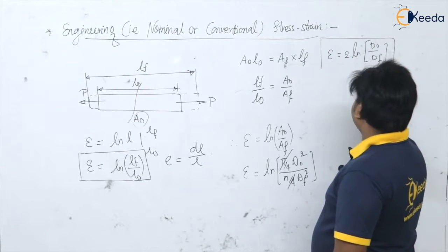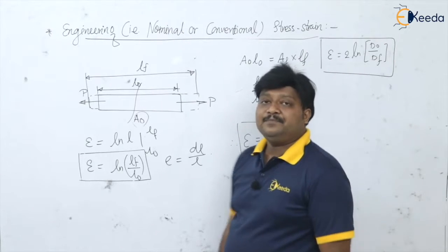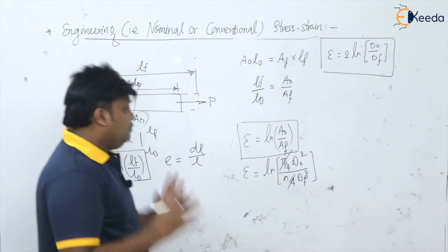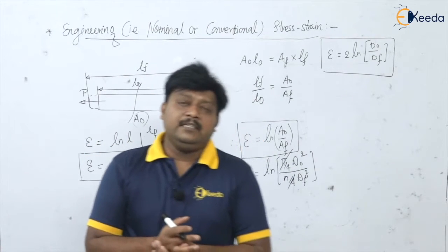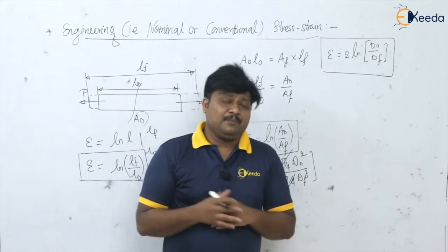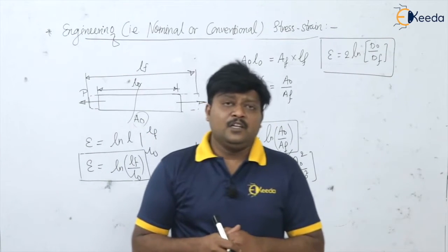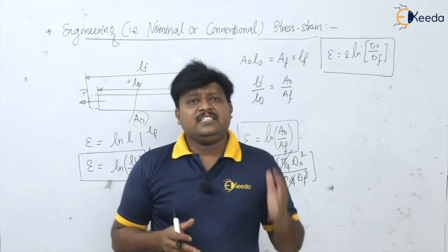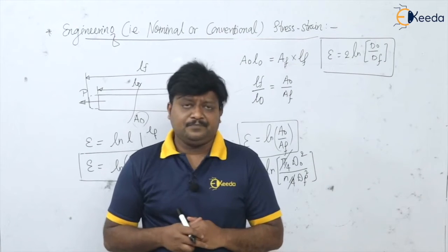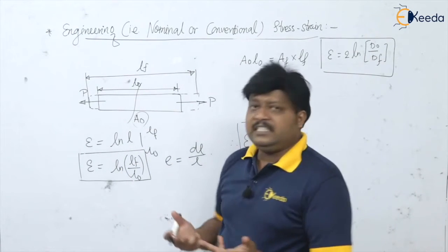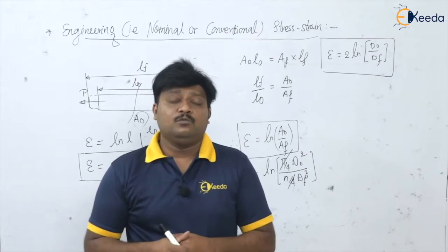So this is also the format or formula for the true strain. Okay, now see here, in metal forming, which stress takes us closer to reality? So which stress is more consistent in the physical phenomena, that we have to see, because both the strains are there, engineering is there and true is there.